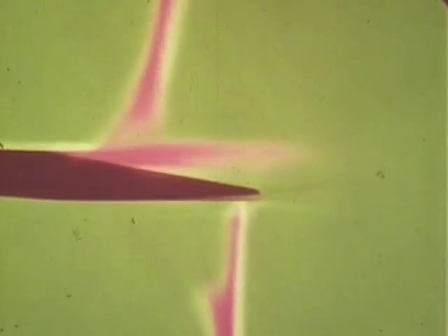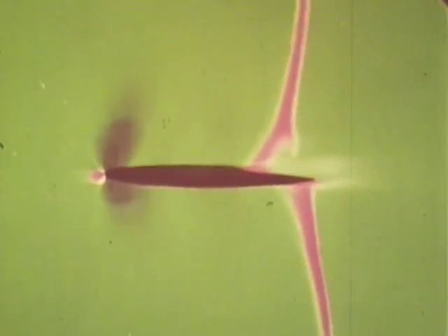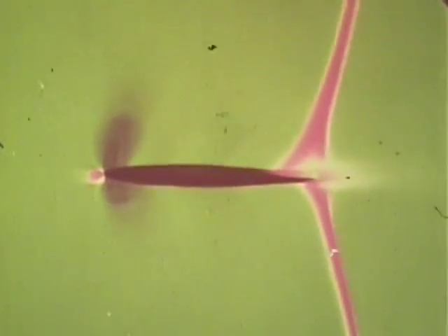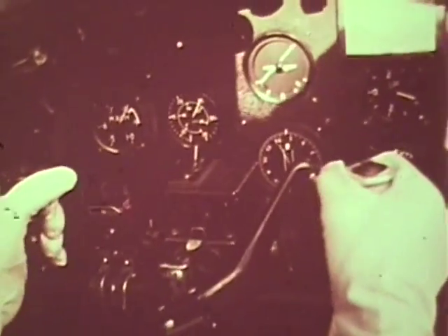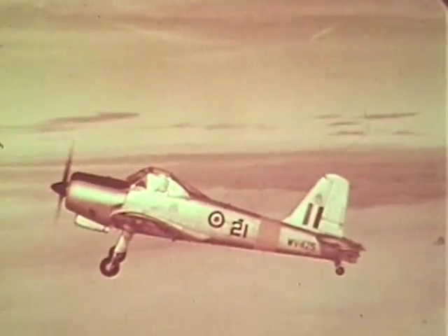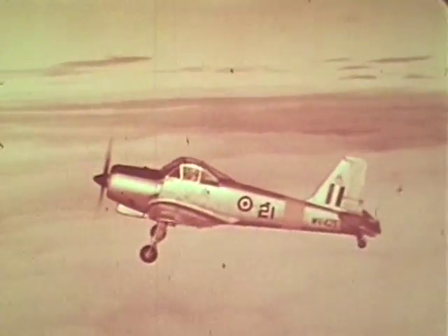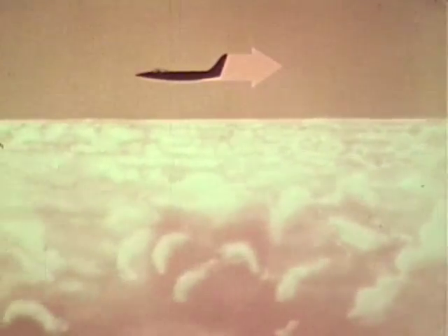But it is flow separation that causes most of the troubles in the earlier part of the transonic range, when separation is greatest. Once the shocks have reached the trailing edge, separation is much less. It is flow separation that causes the shock stall, so-called because the effects in flight are rather like the normal low-speed or high-incidence stall, also caused by separation. The first shock stall trouble is a sharp rise in drag.